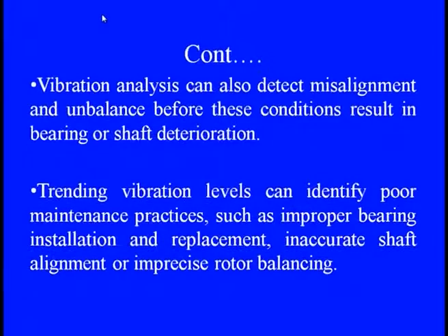So, trending vibration levels can identify poor maintenance practices, such as improper bearing installation or replacement, improper lubrication, so that wear and tear is more, inaccurate shaft alignment, even imprecise rotor balancing, and the gear meshing part, meaning the axial features of the gear mounted shaft.